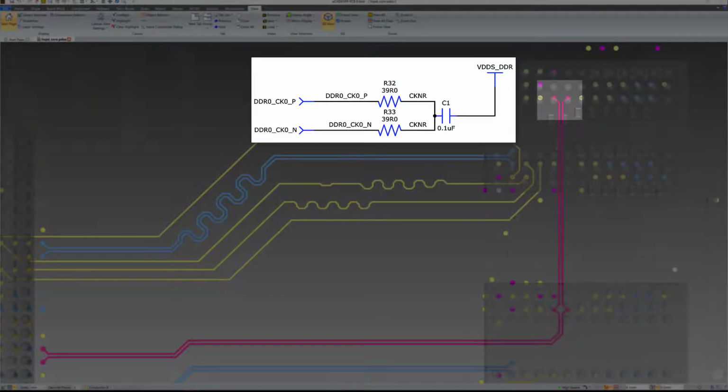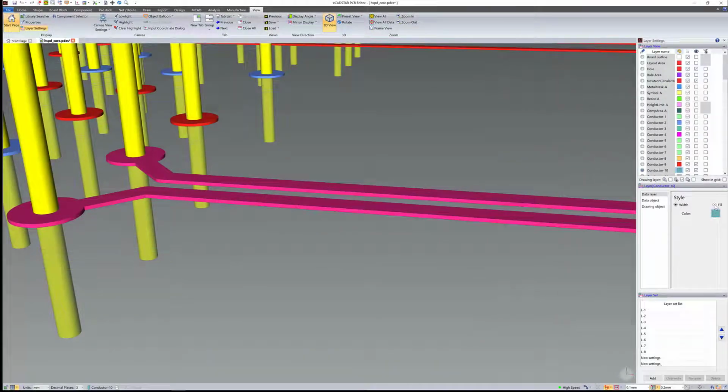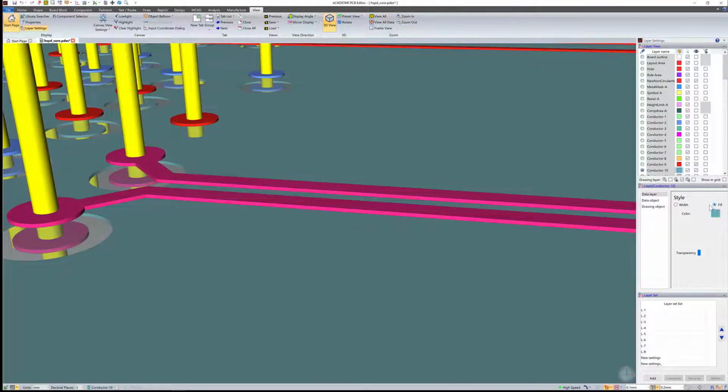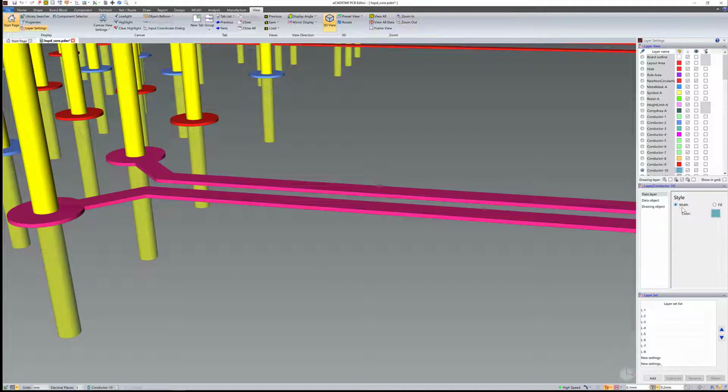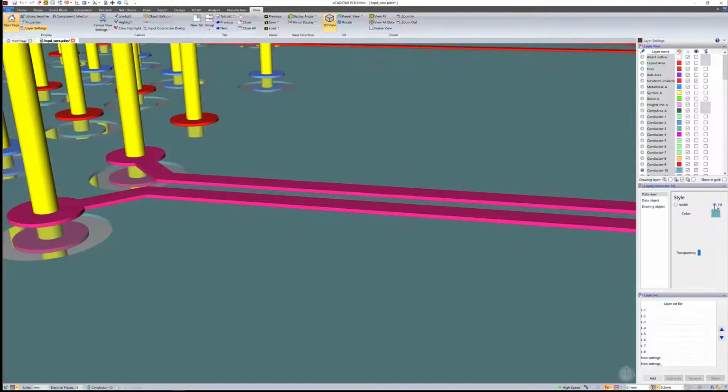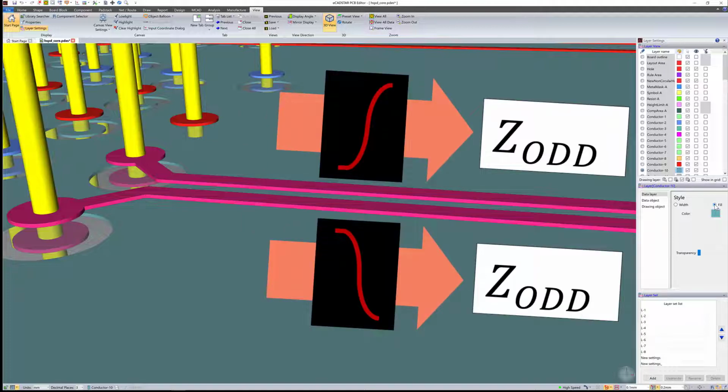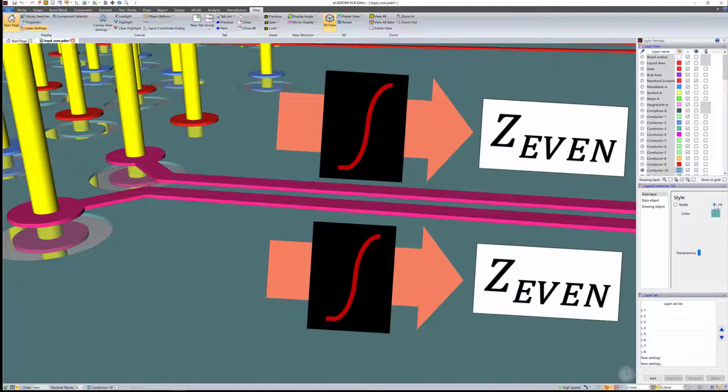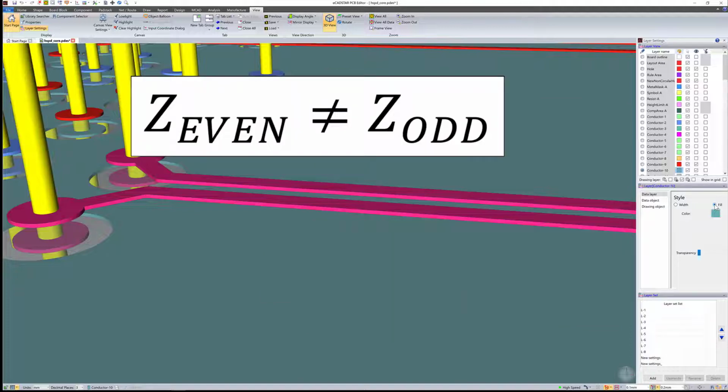the opposite layer. As with single-ended signals, trace widths and nearby fixed voltage and ground planes affect the impedance seen by travelling waves. But in a pair like this, the two complementary sides couple electromagnetically, and that also affects the impedance. The odd mode impedance, where one side is rising as the other falls, as it should, is different from the even mode impedance, where both are rising or both are falling. This is called mode dependency.